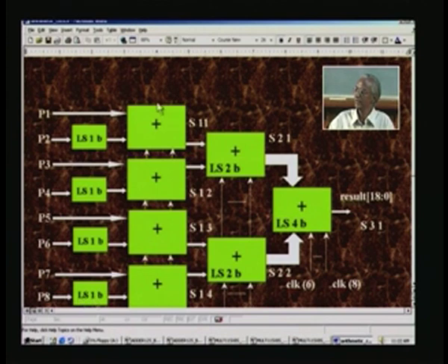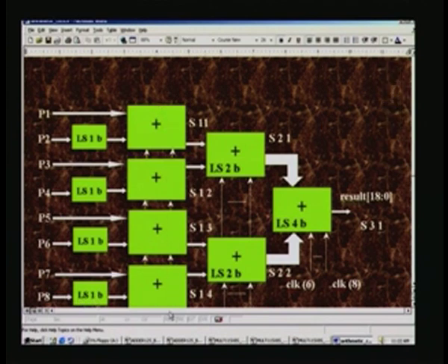So, concurrently you will have all the partial product results here, and that is what we said before, that FPGA or ASIC design is characterized by massively parallel circuits. That is what we have here, and when you see the DCT you will be astounded by the parallelism that will be built in. And also it is highly pipelined in the sense that internally there are so many pipeline registers. For example, 2 registers are hidden inside, and that is the reason why the clock has been input there,